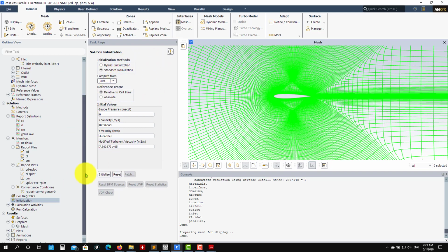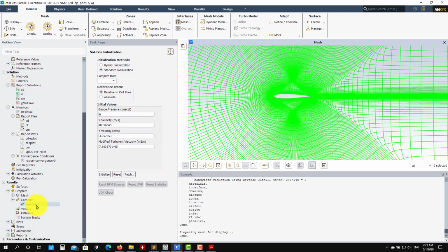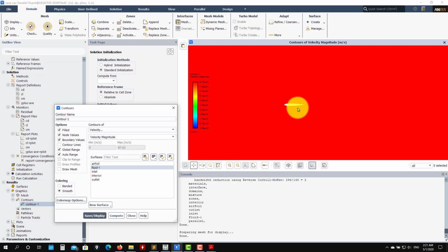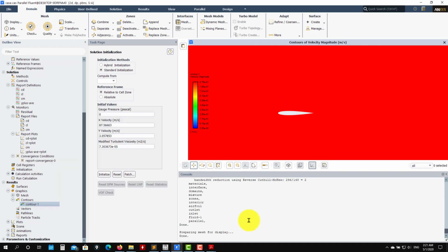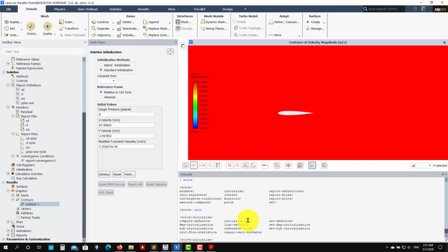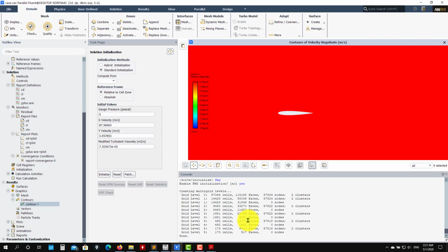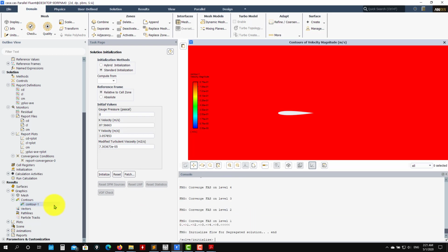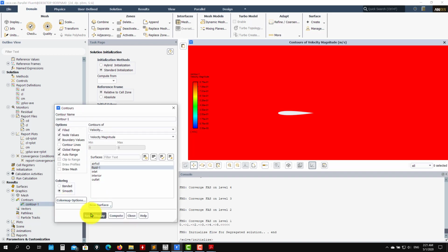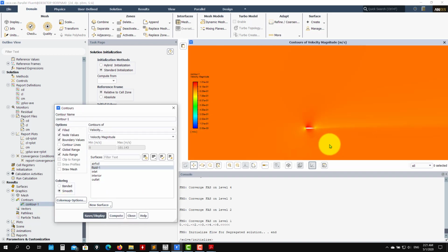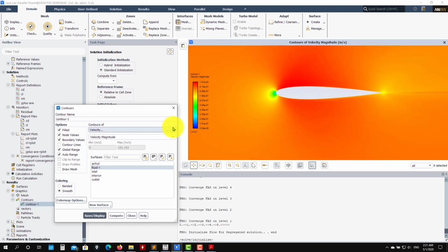Okay, so we added that, then we go to initialization, so let's compute here. See that we have our values initialized. But this is a uniform field, remember. So in this case, we can take advantage of the full multi-grid initialization. Remember that you have it here in the text user interface. So you go solve, init, and now FMG, yes, and we're going to use this initialization, very powerful. I love this method, but as I said in the previous one, it's not available for every case or every physics, okay? So see that we have a very good initialization also for pressure.